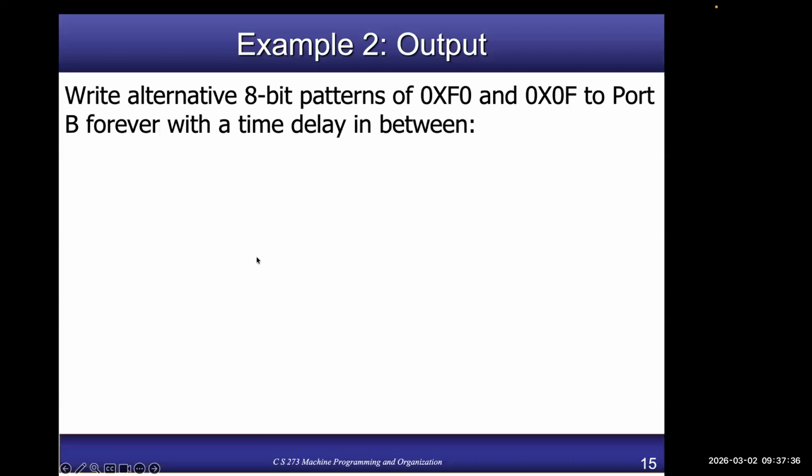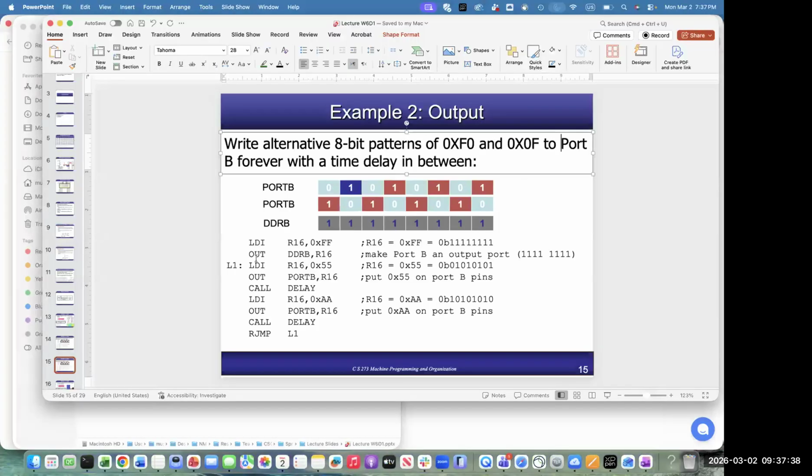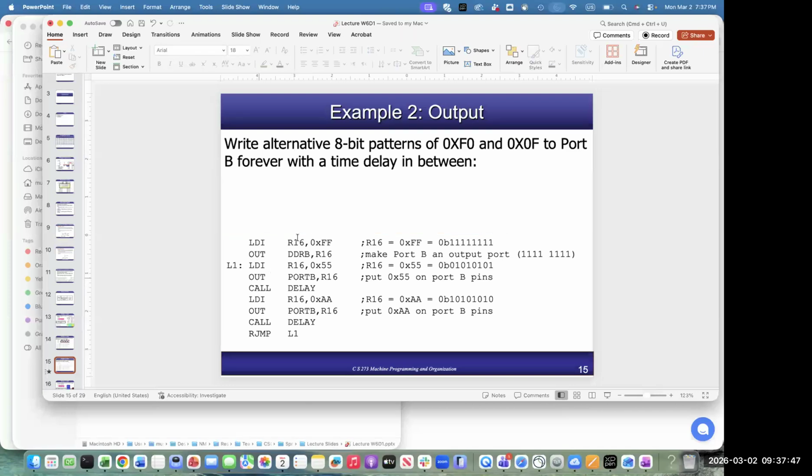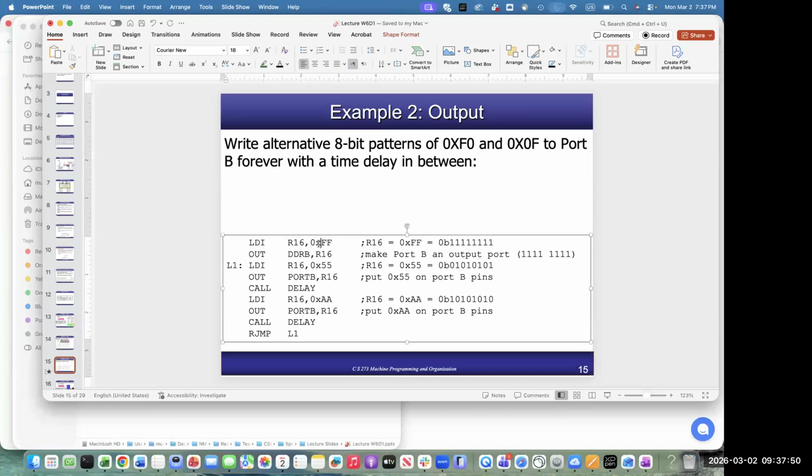Okay. So yeah, I can simply modify this one for you, right? I am deleting these figures to not confuse you. In load immediate, here you can simply first put 0xf0. I am also deleting the command, oh sorry. So you can first put that to configure the DDRB in R16. I think I can keep this one, right?